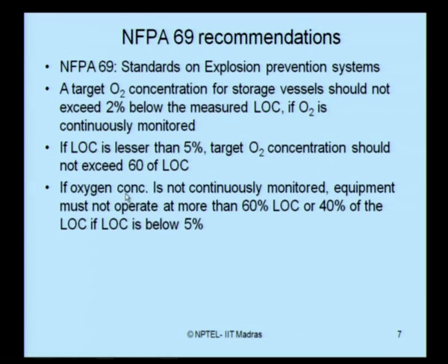If the oxygen concentration is not continuously monitored, then the equipment must not operate at more than 60% of LOC, or 40% of LOC if LOC is below 5%. Ladies and gentlemen, NFPA simply recommends a target oxygen concentration based upon your LOC.